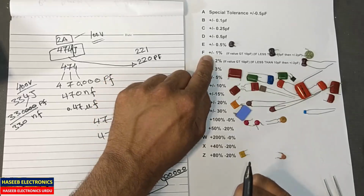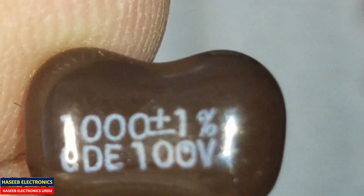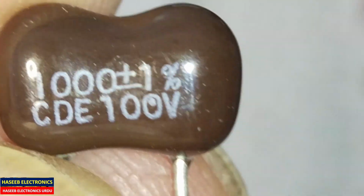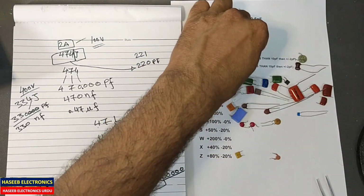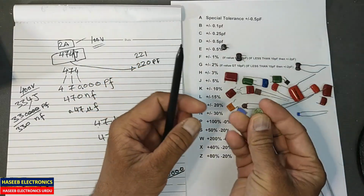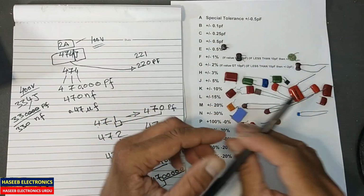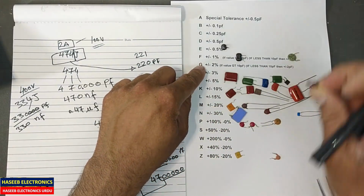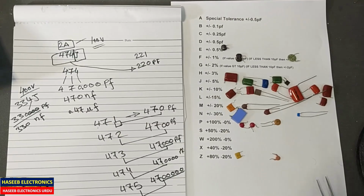Then there is F, plus minus 1%. It is 1000 picofarad plus minus 1%. Plus minus 1% means it is category F, so we will place it in category F. The same is here, 5F. 5 picofarad, 1%. Then G, it is plus minus 2%. F271G. So it is also a special capacitor for frequency generators, synthesizers.